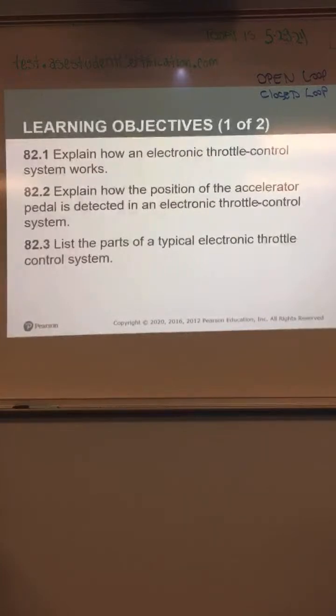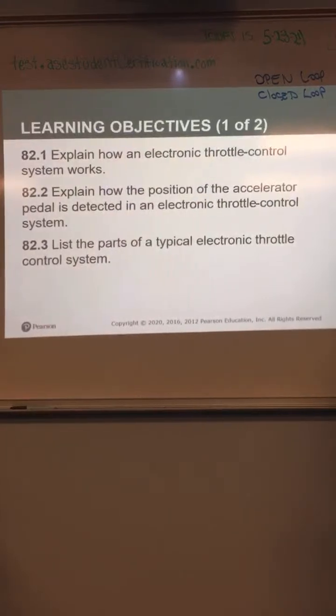What were those things usually for? Is it just to get air in when they give it gas? You know, they have those three tubes on the muscle cars, that huge thing. He's talking about the blowers. Like when you gas it, three of them open like this. That's the same thing as that, it's just three of them. That's just for more throttle plate air, yeah. But it's exposed, so you can actually see it. They don't run air filters on them. What does it really do? More air in it? Yeah, they're typically on a roots type blower, sitting on top of the blower. So the fuel's injected down here and you're getting the air on the top, but that's typically just race car stuff.